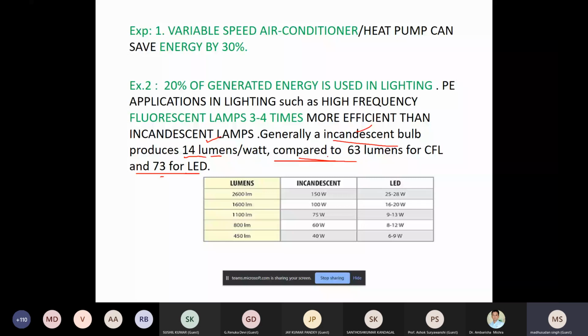Earlier we had a conventional starter, star delta starter, using especially contactors and timers. And especially if it is a very high rating machine, say a 500 or 1000 kilowatt induction machine, the size of this starter is very bulky. Nowadays, if you see, this is all done through drives. So drives do the job of a starter also.